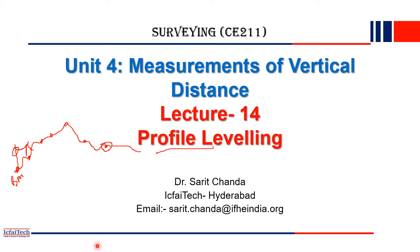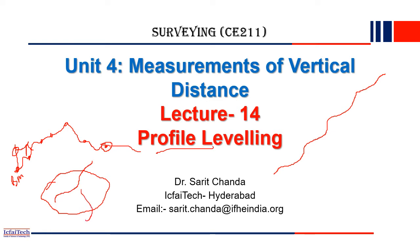What is profile leveling? For example, you want to construct a road or a railway track in a city or a region. Railway lines go through in a linear path, or maybe a highway road, which also goes in a linear path, crossing the region. In that case we have to track the profile of the terrain. So in a linear fashion, how the ground is varying, how the depth and elevation are varying, that we have to find out, and we call it profile leveling. So let's get started.